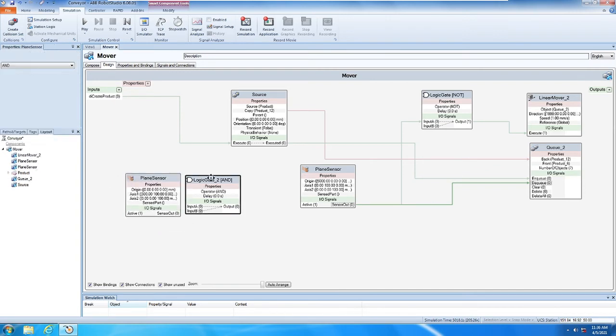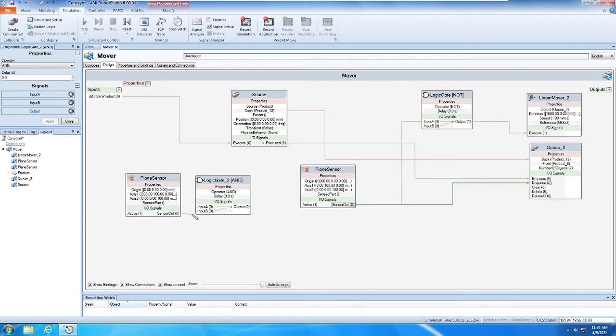This is number 1 priority, and this one connects to A, and I want AND logic. This one, sensor out. No, we can't use this one. This has to be off, clear. If this is on, then something's there, but we need the opposite logic.